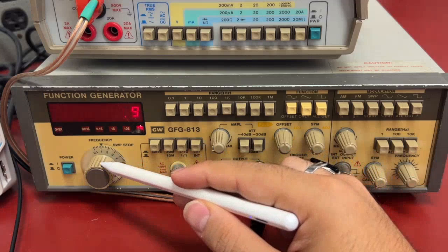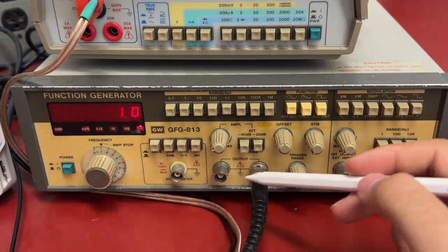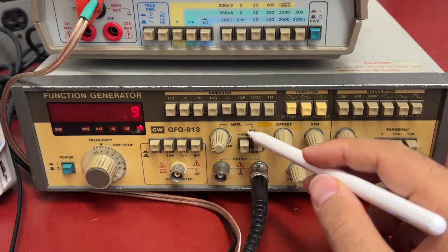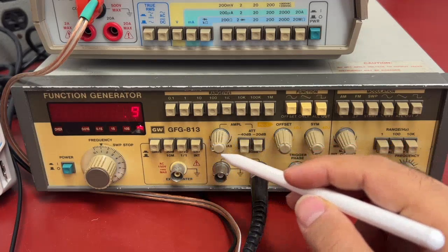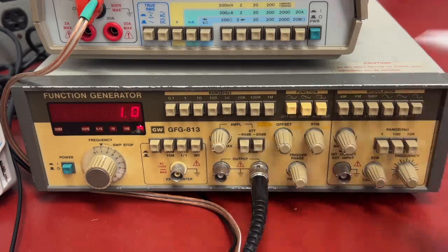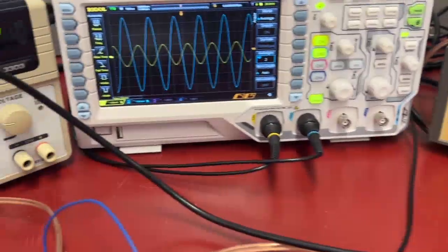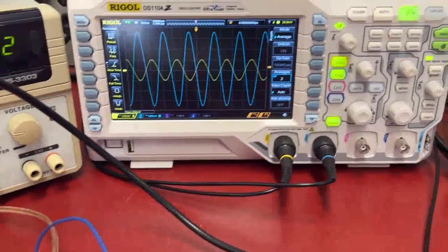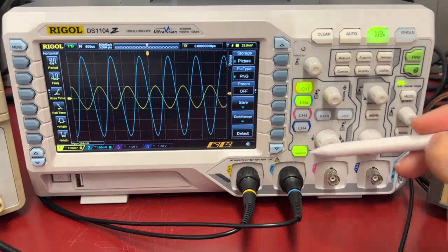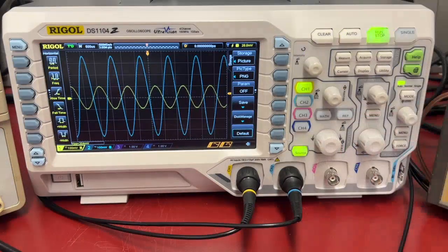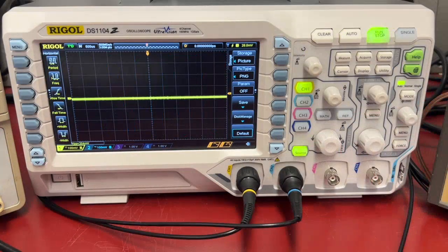For the signal generator, do not forget to use the main output connected to your circuit. Also, to generate low amplitude signals, you need to activate the -20 dB attenuation provided on the signal generator panel. On the oscilloscope, always start by pressing the storage button followed by the default setting to load the default setting of the oscilloscope, to prevent any unintended setting that may be applied by the previous user.